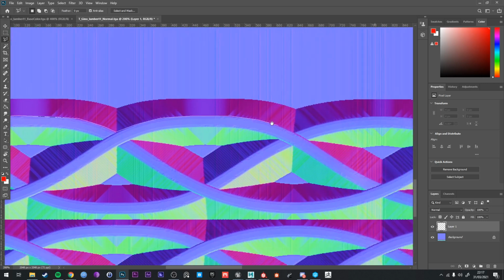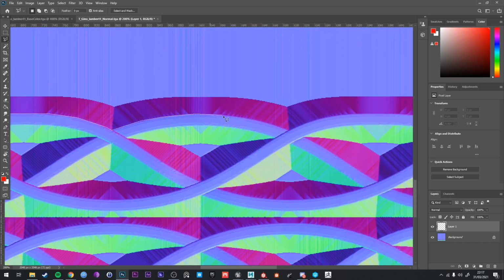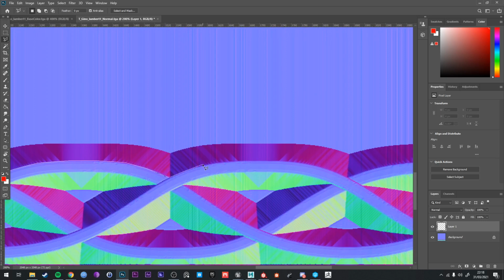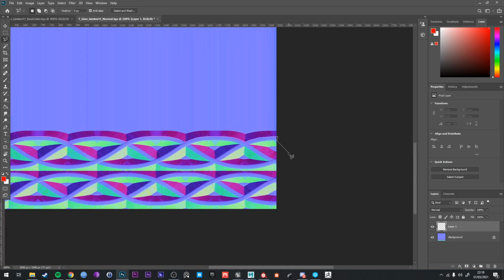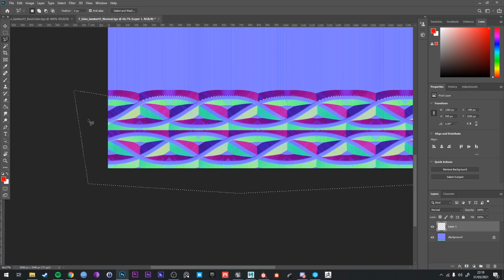Sometimes, depending on what you're working on, the thickness map will basically already work as an opacity map, and you just have to export that by going to export mesh maps from Substance Painter. Mesh maps are the maps you've made in the bake, remember? So all the ones that Substance Painter uses to apply your masks. And you just export that, bring it into Photoshop and just tweak the levels. In this case, we have to do it by hand, sadly. But it should be the same all the way along. So I'm hoping I can just do one part and copy it to the other part.